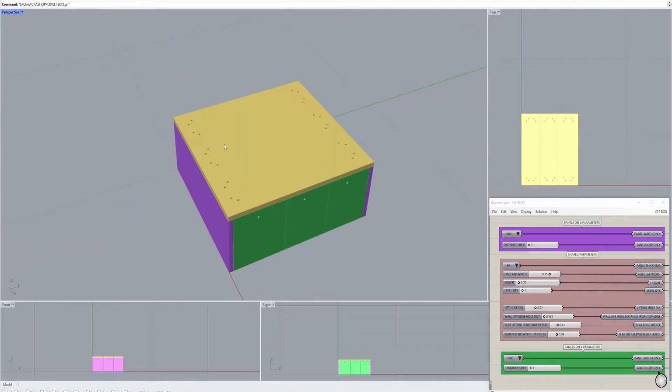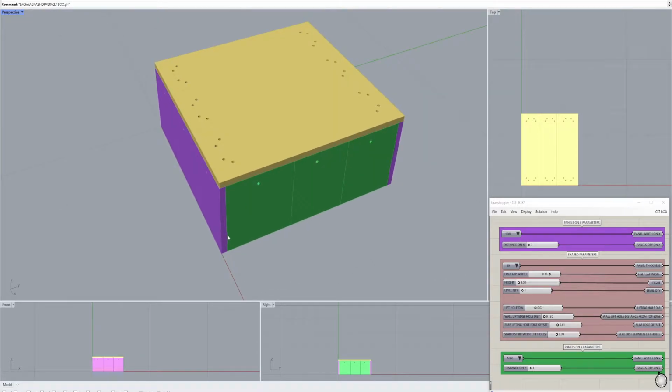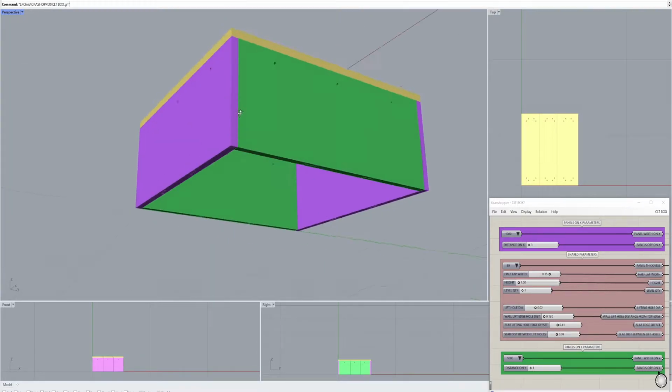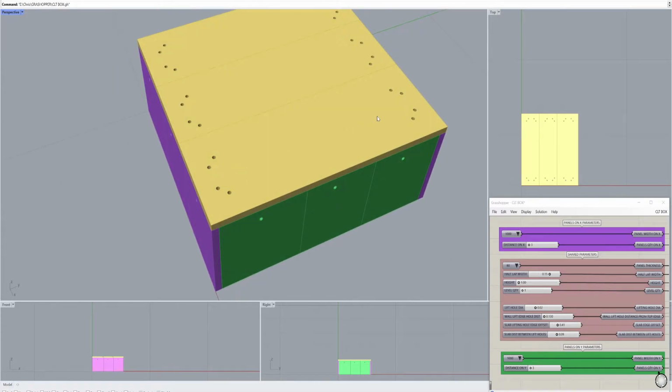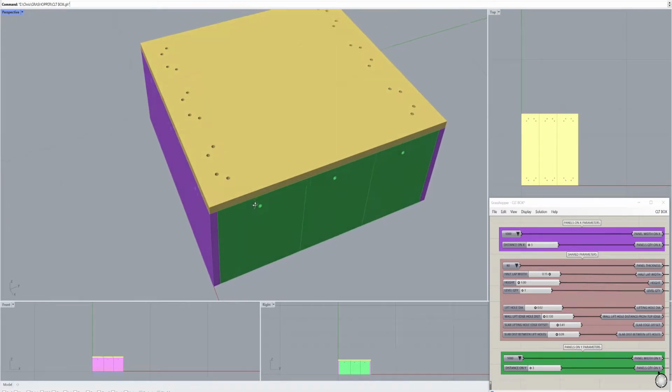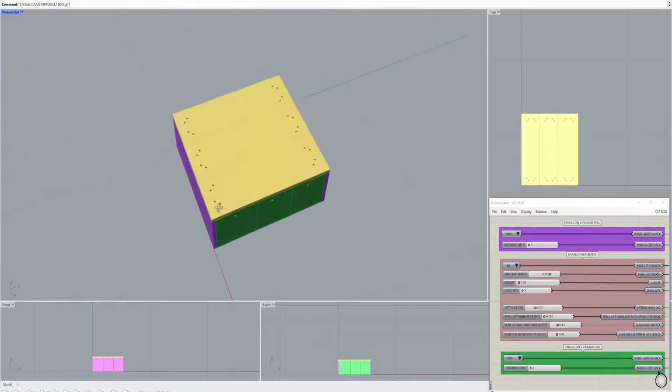I did have the slabs also going the other way, but you basically have to change the arrangement of the walls. So here, the slabs that are spanning this way on the Y, the walls on the X are basically sandwiching the walls inside of the Y. And so if the slabs span the other way, I have to change that arrangement. I thought about creating 2 different paths that are controlled by length.